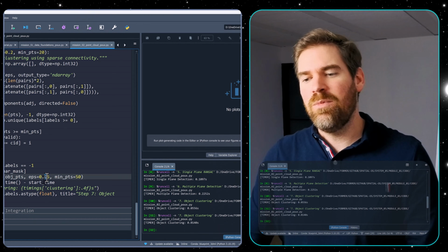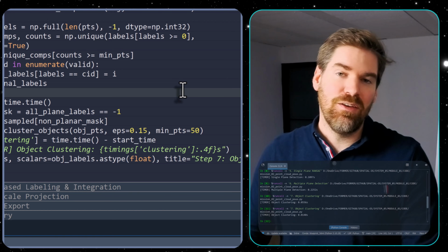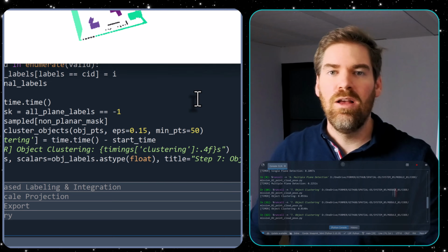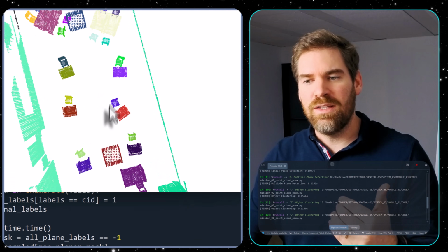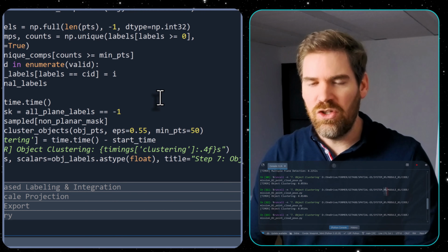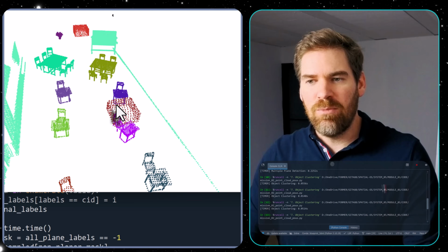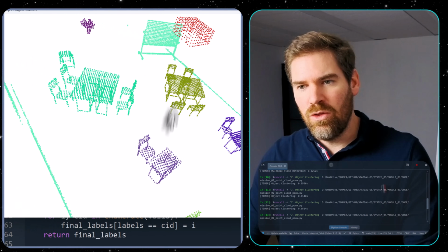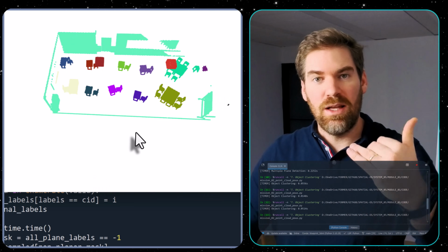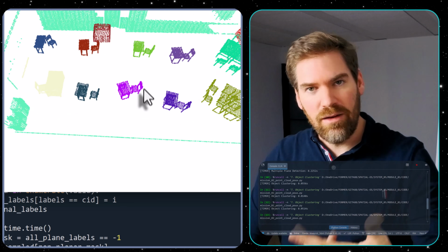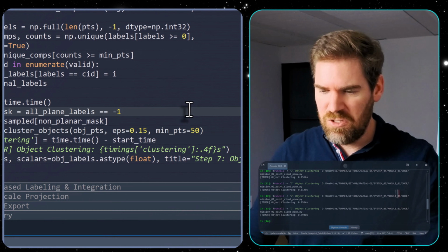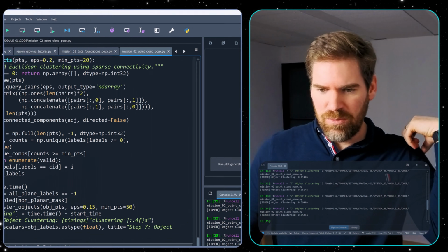And this can be optimized based on the sampling of the point cloud that you made. So if you did voxel downsampling at 0.05, if you take 3 times higher, maybe it's a good idea. If you go much bigger, like 55, you may have an issue with under-segmentation, where the groups that you have are much bigger. So it's nice to understand the relationships at several levels, where you could have this multi-layered segmentation approach. Okay, so let's stick with this 15 to have something pretty cool.